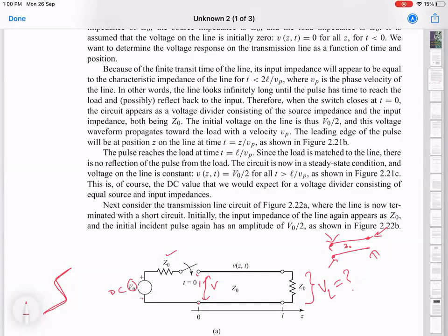In fact, it's a signal with almost infinite bandwidth going all the way from DC, because it's an instantaneous rise. So you'll have Fourier components all the way, becoming smaller and smaller. So the moment you look at the picture of the transient, you go back to your standard AC picture. The important point is that it's a dispersionless line, so all frequencies are traveling at the same speed.